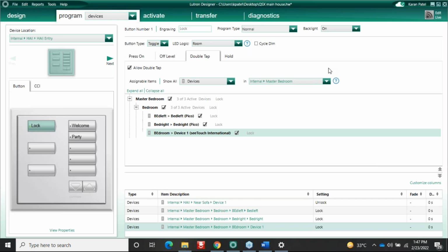So for the passages and the lobby lights, I use a higher fade time of 30 minutes, a smooth fade. In the restaurant also you can do the smooth transition. Also, if you want to make a baby sleep in the kids room, I typically make a good night scene where the light fades very smoothly over half an hour. The kids go to bed and the lights smoothly fade out from 100 to 0% in half an hour. So these are two examples of using a higher fade time.